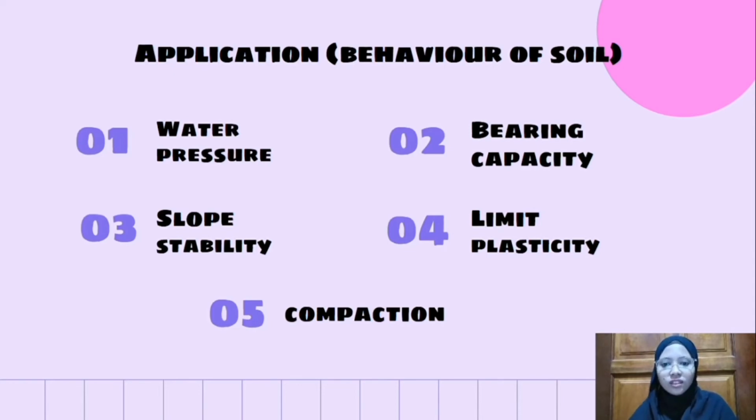Next, the average contact stress between a foundation and the soil that will cause shear failure in the soil is known as the bearing capacity of soil. The allowable bearing stress is decided in reference to the utmost allowable settlement because large settlements may occur under loaded foundation on soil site without actual shear failure.